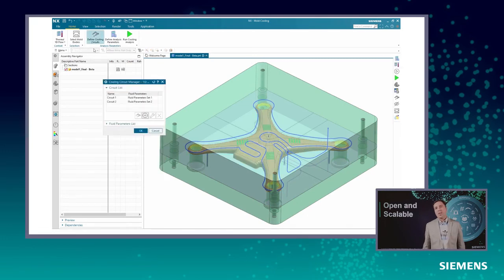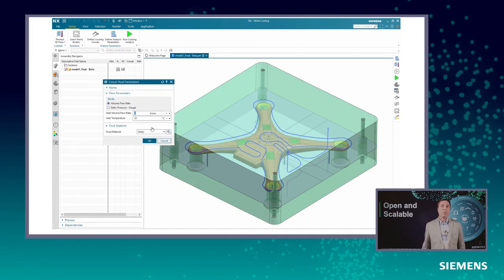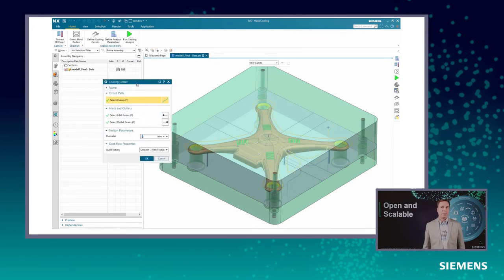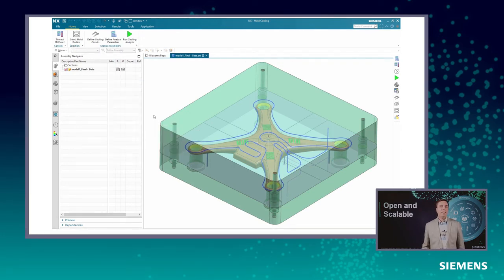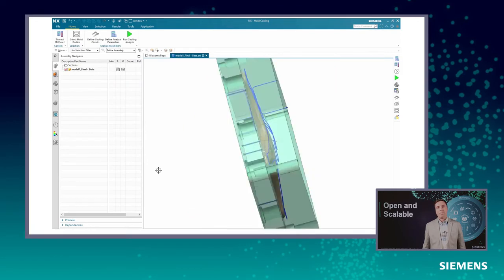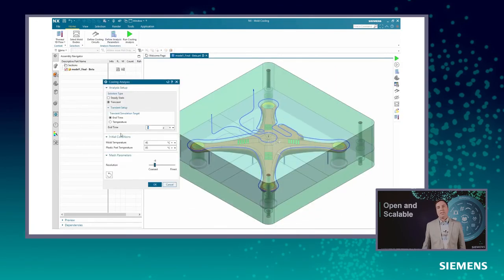This new solution is called NX Mold Cooling. The traditional approach for thermal analysis of a mold design requires a significant manual preparation and care to mesh the small cooling channels. This can be tedious and prone to setup errors. The new NX Mold Cooling product lets designers rapidly set up and simulate the thermal performance of an injection mold insert directly in NX. The wizard-based interface and fast, robust meshing make it easy to use yet powerful to validate your thermal designs.